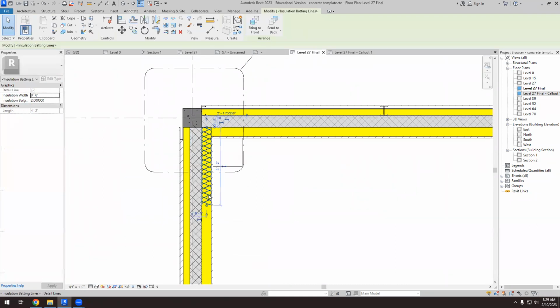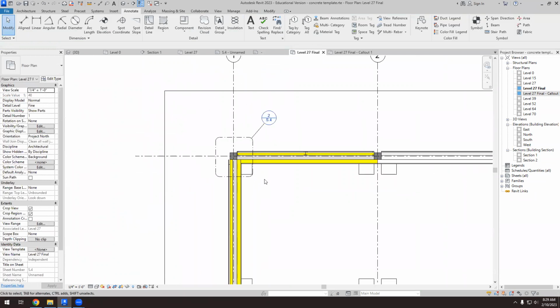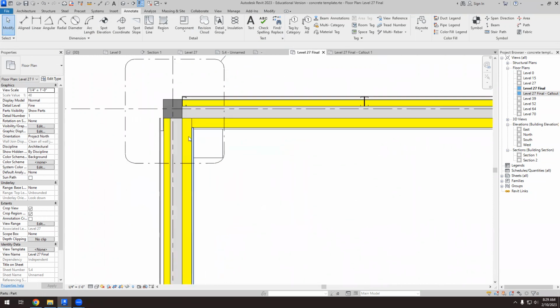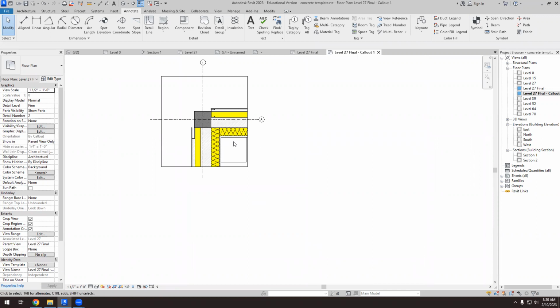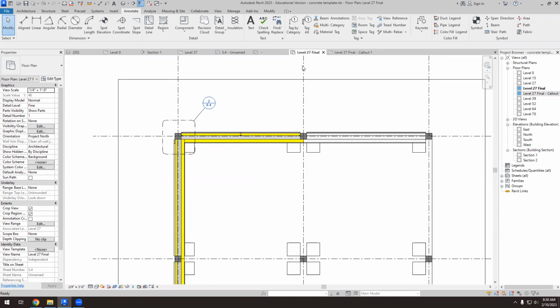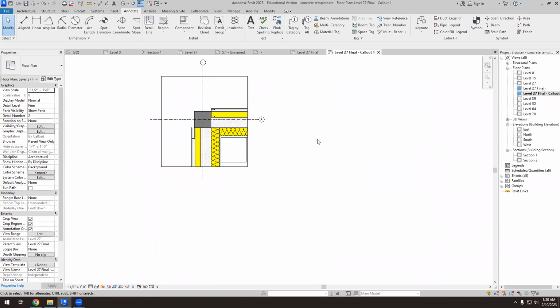And before adding a lot of details here at that scale, we have to print it out to see what it looks like. Because if we add a lot of details at that scale, then probably we will have like a black corner, and all the work that we have done is not showing. It's even worse than just leaving the detail blank. So that's why we have to be careful with the level of detail that we have with the plan that we are showing and the callout.